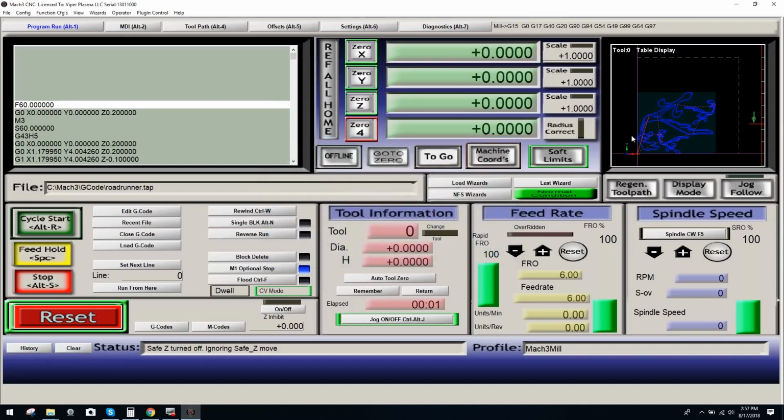Now, again, the soft limits are very smart in the sense that if you're moving and you accidentally, like I said, I get guys who sometimes say, if I move over and I forget, even on my Z, let's say they're jogging positive and then they go to move up on their Z. Now you can see, here's another mistake that'll usually come up. You hear how it keeps chiming? Most of us already know why it keeps chiming, because we've already set our 0 and we're a thousandth over where our 0 is set. You can't reset this like standard, because if you go to reset it, you're going to keep getting the same chime. Why is that? Because we have our soft limit button enabled.